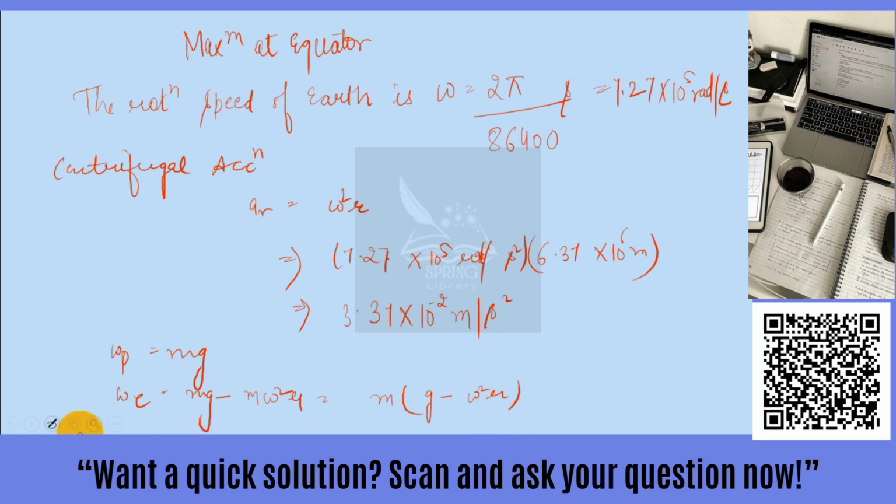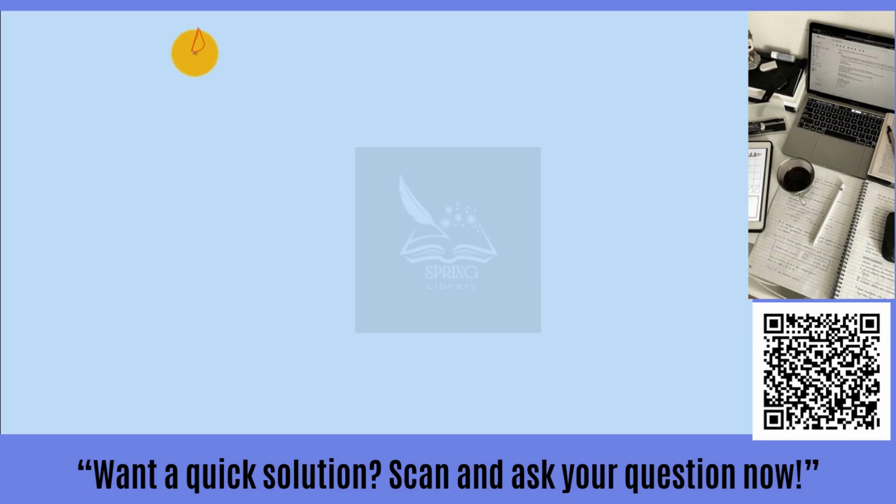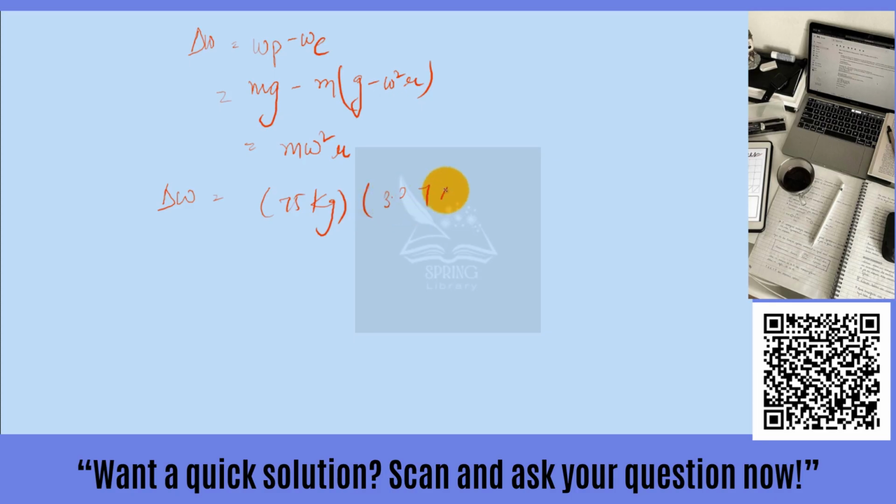Hence the difference in weight, delta W, is equal to Wp minus We, which is mg minus m of g minus omega square r. Hence we get the value m omega square r. Now substituting the value, we have delta W is equal to 75 kg multiplied with 3.37 into 10 to the power minus 2 meter per second square. We get it equal to 2.5 Newton.